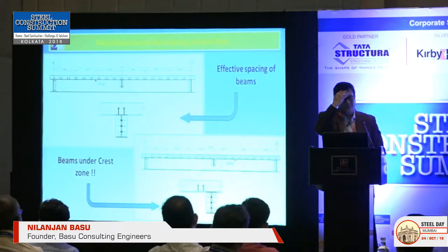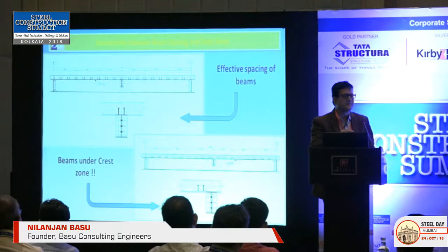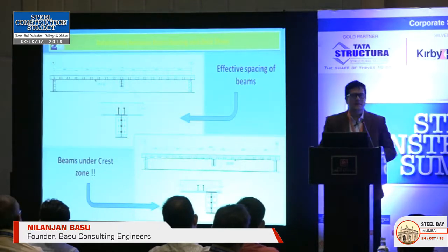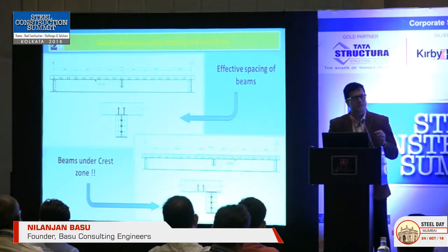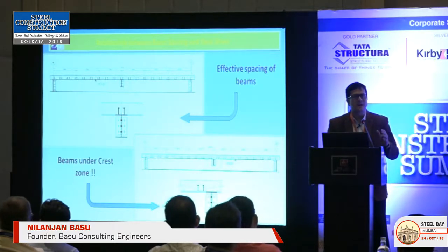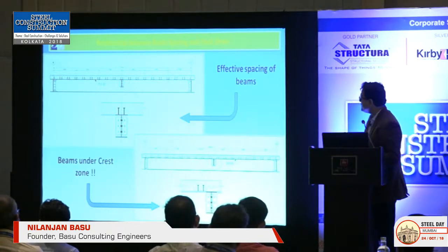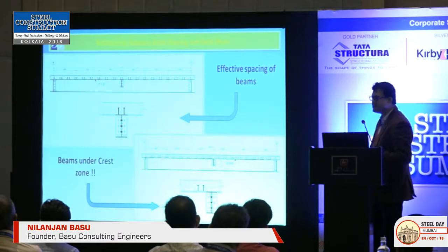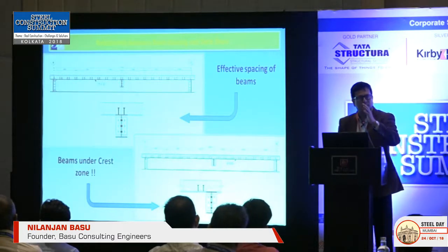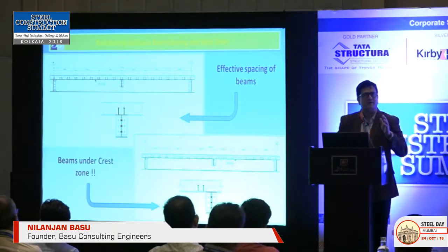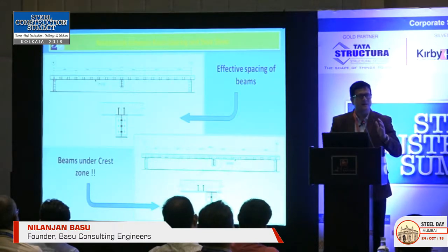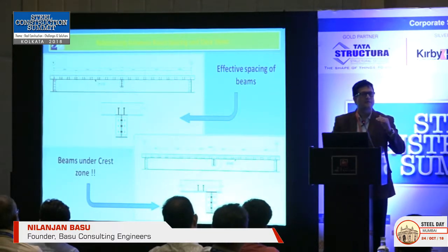Okay, now during the pre-construction or the pre-planning stage with the architect, I also mention a few things. Whichever deck system we are using, we generally ask the width of the deck. The width of the deck is very important. I'll tell you why. Because once you place the decks one after another, you don't want the crest of a metal deck to fall just on top of the flange of a beam.